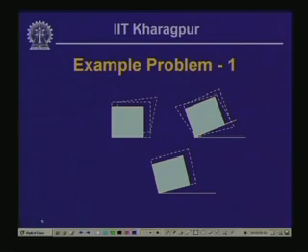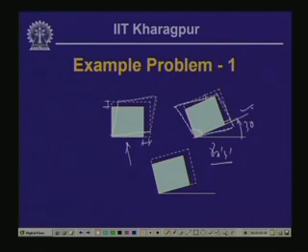Now, once this particular element undergoes strains, this is the configuration which we expect. In the initial stages we had epsilon x as 340, epsilon y as 110, and we had positive shear, which is denoted by this as 180, and this is the orientation of the element in initial strain. Finally, when it is rotated at an angle of 30 degree, now it has epsilon x dash, epsilon y dash, and gamma x dash y dash is negative. So, the angle here increases, and this is the form which it takes, and so this is the final shape of the body after it has undergone the strain.